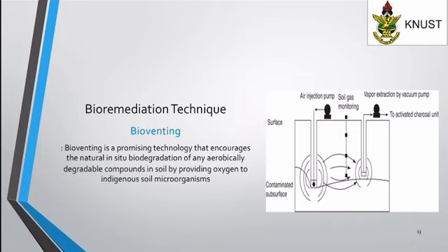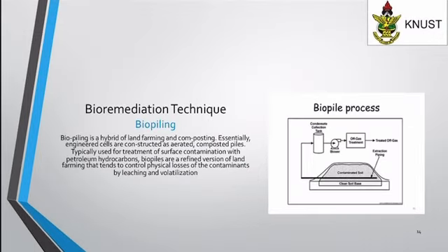Bioventing. Bioventing is a promising technique that encourages the natural in situ biodegradation of any aerobically degradable compounds in soil by providing oxygen to indigenous soil microorganisms. Biopiling. Biopiling is a hybrid of land farming and composting.